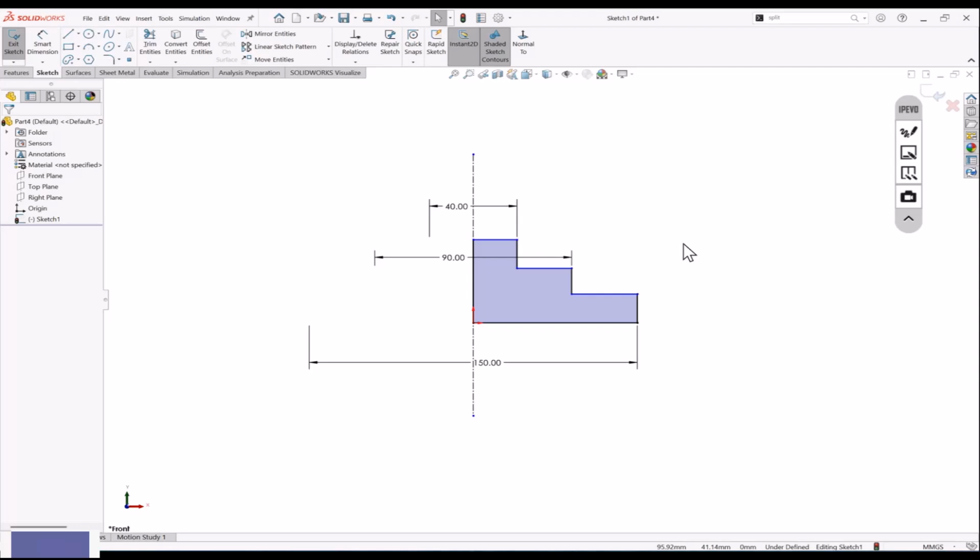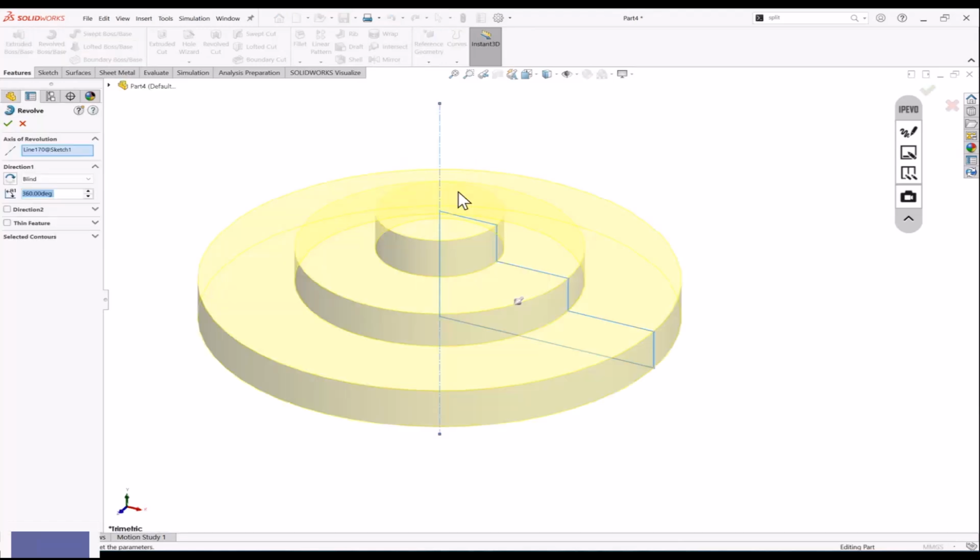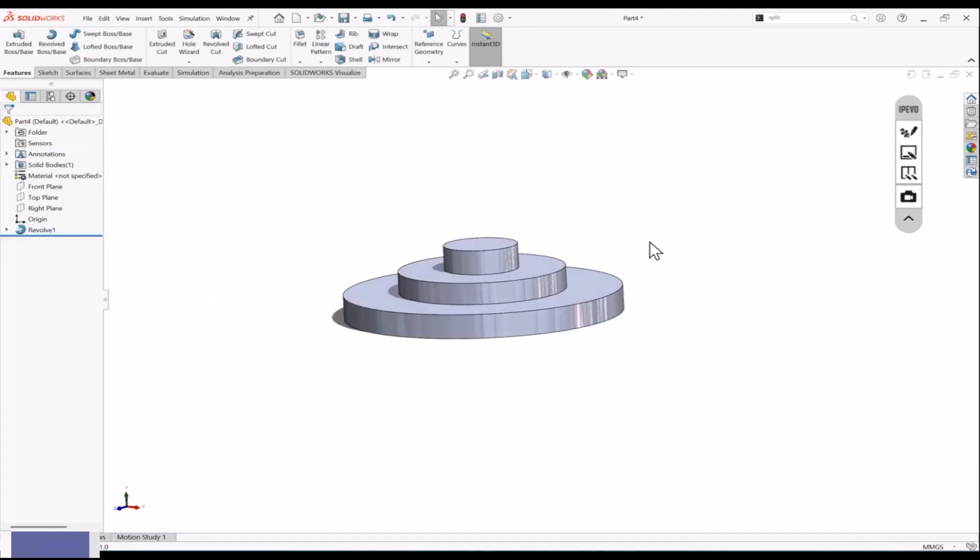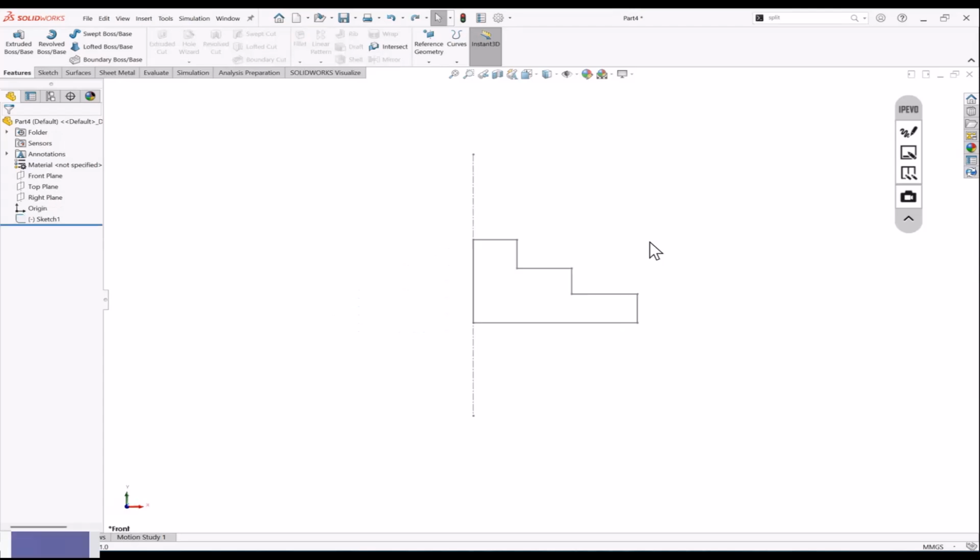When you're making the complete diameter from 2D to 3D, for example, in this 2D the complete dimension is given. But you're making a revolved part. In that, we draw only half of the cross-section. So either you calculate the half dimension and do it, or you say, I don't want to do any calculation. In that case, you use this method. The software will add it for you and you can do the dimension. The benefit is I can just go and revolve. I don't need to worry about what the sizes are, because I gave the correct sizes. I don't need to calculate. So that is the advantage.